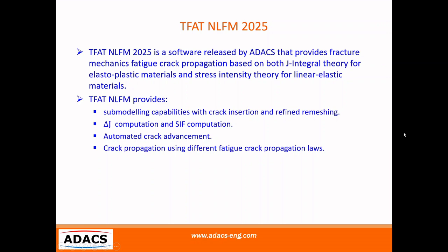TFAT NLFM 2025 is a software released by ADAX that provides fracture mechanics fatigue crack propagation based on both J-integral theory for elastoplastic materials and stress intensity theory for linear elastic materials. TFAT NLFM provides submodeling capabilities with crack insertion and refined remeshing. So you can submodel your global model, insert a crack, and remesh this cracked submodel with the mesh being refined around the crack front.